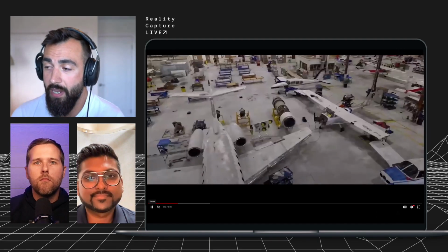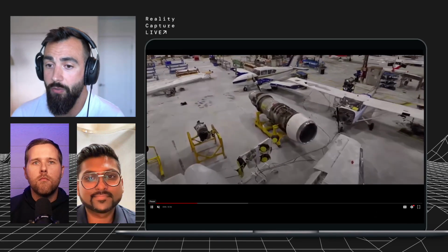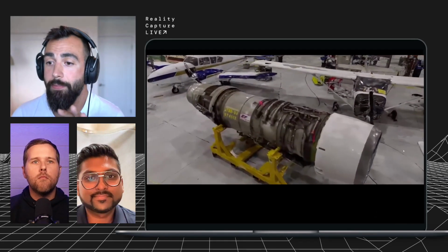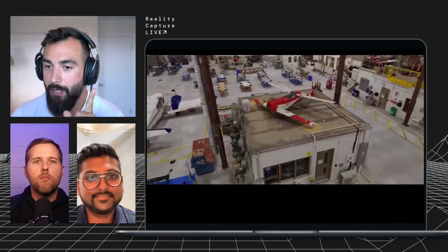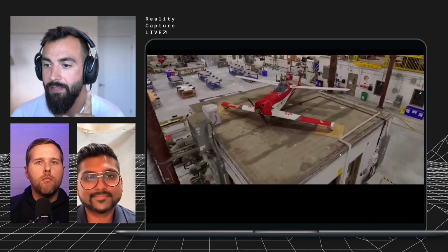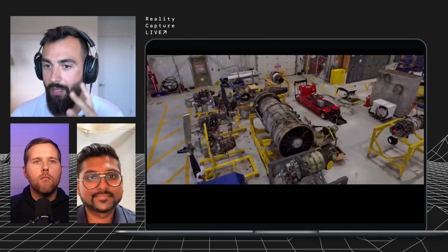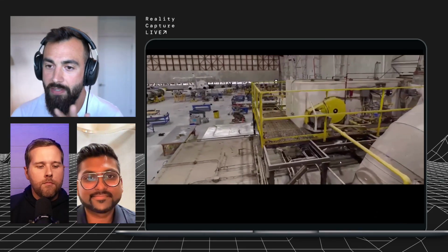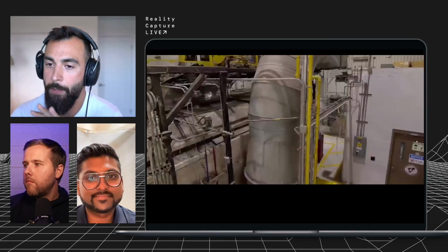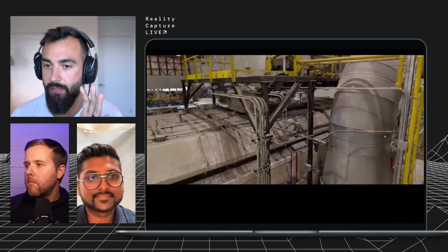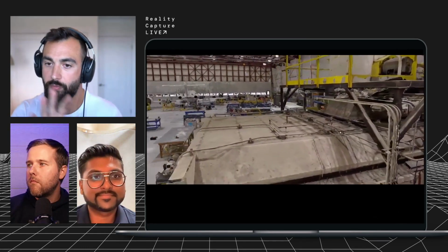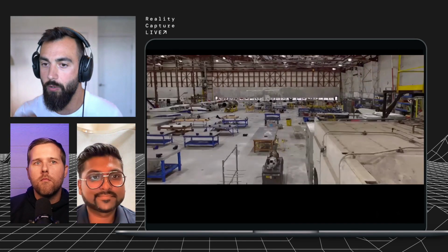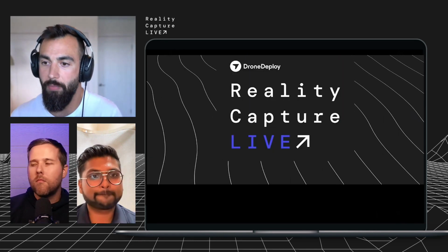With the SkyDeploy, the way to do this was to break it up. So again, photogrammetry is photogrammetry. It doesn't matter how many days it takes you, or if you visited once a week to collect it all. As long as nothing really moves too much, you can chunk it out and collect one corner and then move over to the next corner and the next corner, etc. So in combination of all of those chunks, this was about 8,000 images.